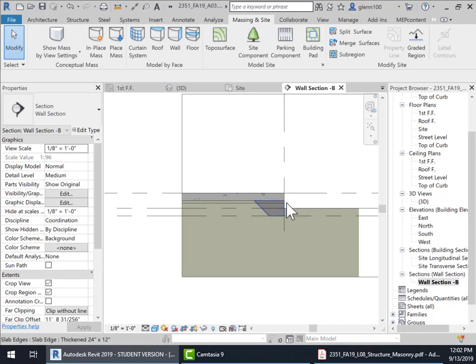So we can see the edge footing sticking outside the topography. And of course that would probably be sloped a little bit away from the building with at least a 6-inch exposure of the concrete until we get our brick in there. Okay, so now the foundation's finished. The next thing I'm going to do is do some concrete block walls, which should be pretty straightforward. So I'm going to end this video here and we'll do another one that's on walls.